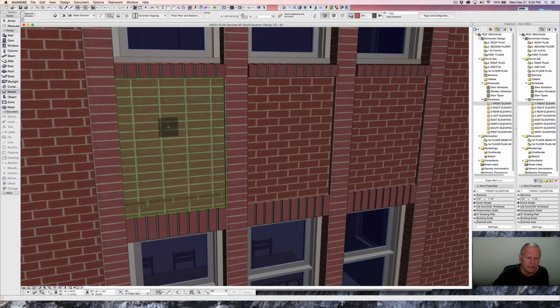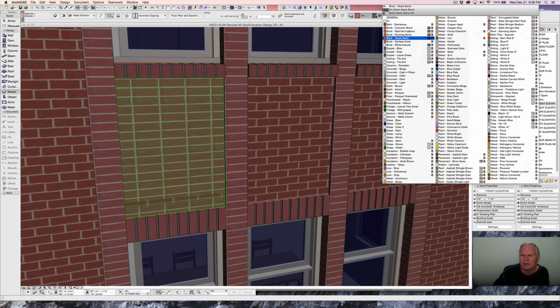So the first thing though I want to do is put my herringbone in, and not the stacked bond. So what I'm going to do here is go up and in the surface settings here, click on this, and I know that what I want is a herringbone layout that I think I've done before, so it might take me a minute here to find it.